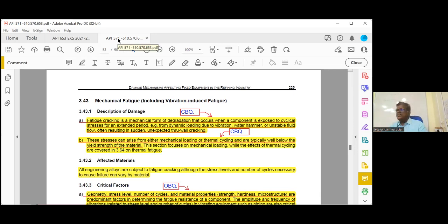That fluctuation range is called IOW, integrity operating window. But if it is fluctuating excessively, then it will fail below yield strength also. It will fail so quickly. That is called fatigue failure. Fatigue failure, cyclic loading, means pressure going up and down or temperature going up and down.